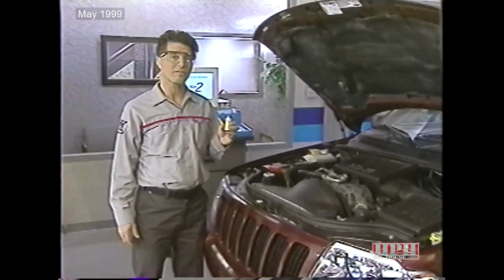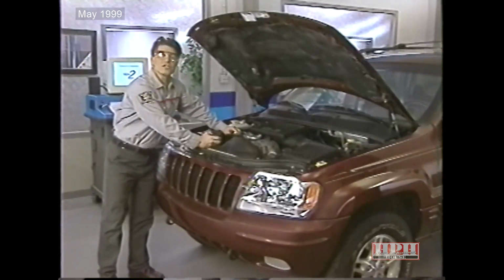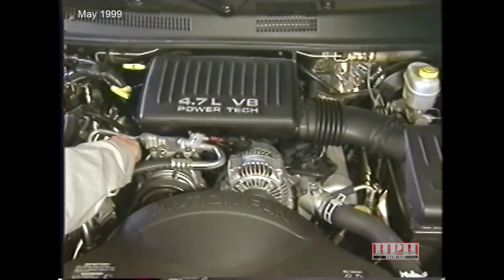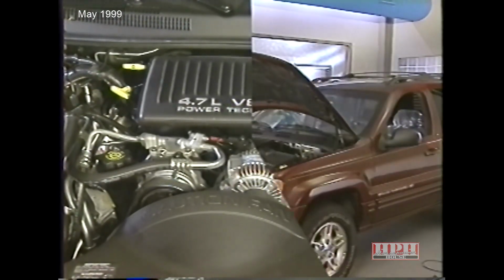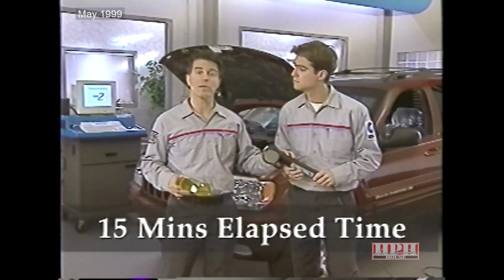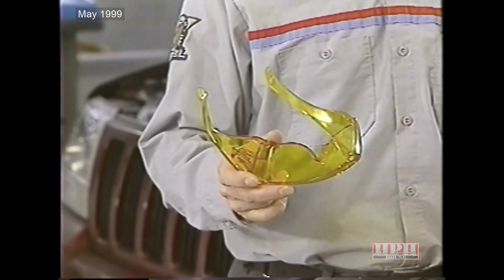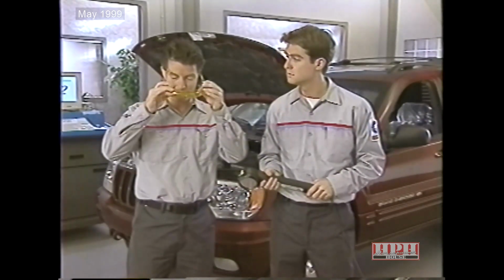Now we'll add the specified amount of soluble dye to the oil. Then we'll start the engine and run it for about 15 minutes. This allows the dye time to mix with the oil. After 15 minutes, using the ultraviolet light, we'll check the dipstick for the dye to make sure that the dye is mixed with the oil. To make this easier, we'll use these dye-enhancing glasses that are available through Pentastar Service Equipment.